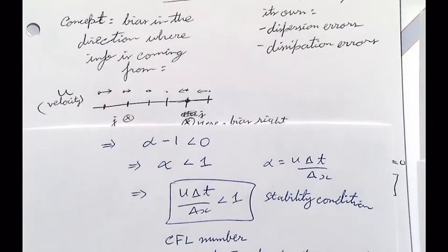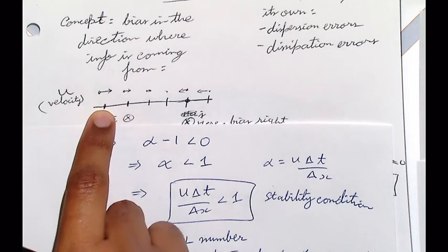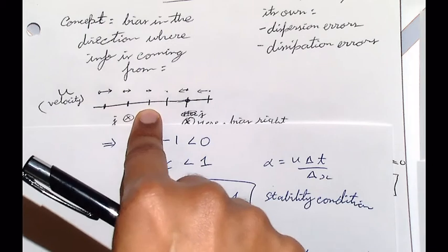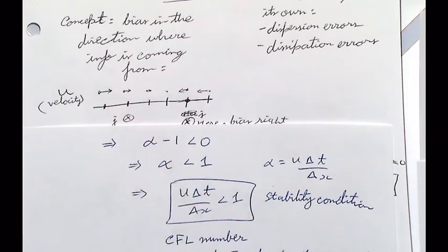What would that do? Physically, it will mean that you only go 0.1 seconds at this node, but you go 0.4 seconds at this node. Now there is an imbalance, right? You're not at the same time, so you cannot proceed any further. So what you do is pick a smaller one. Picking the smallest delta t.